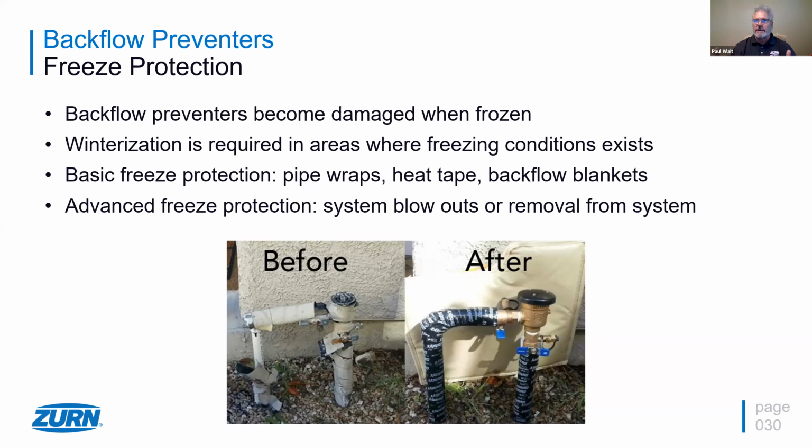So backflow preventers do become damaged when they are frozen. I get a lot of people trying to return products that have been frozen and they're cracked, and there's no warranty for freeze protection that hasn't been implemented on a backflow preventer. So if you don't winterize the valve and it breaks, it's out of warranty. So the winterization is required, and that's the key part here in this slide.